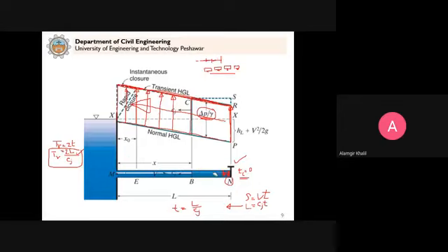If we consider any point which is less than L, let's say I consider this distance x, then when the pressure wave starts at B, it goes here to the reservoir. How much time will it take? Now the distance is x, so the time will be x by Cj, just as L by Cj was for the full length.